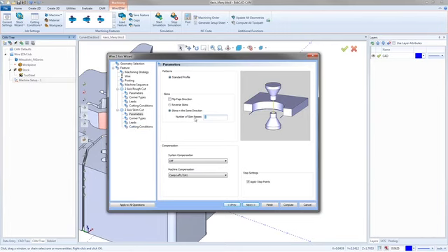So I'm going to leave it at 1 for now. Standard profiles is going to go in, make its cut. You could flip the pass direction. So if the first one went, we'll say clockwise around the part and made the cut, the second one would go counterclockwise and it just comp to the other side.